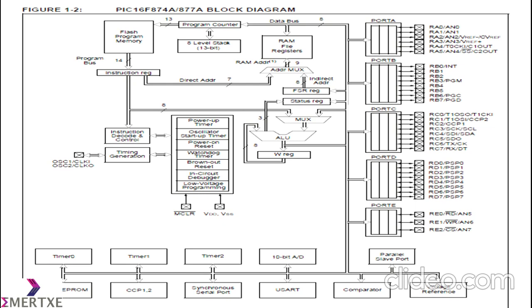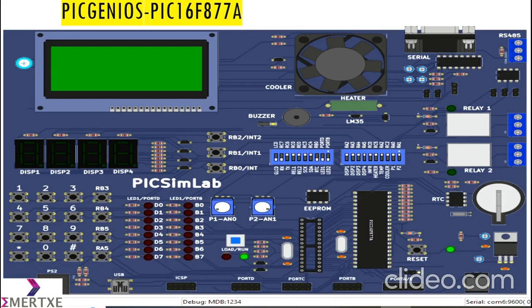When it comes to memory, we have a classified memory hierarchy. In the PIC16F877A microcontroller, the memory organization is classified into 3 sections. We have program memory and data memory. Along with these two memories, we also have data EEPROM and flash program memory.